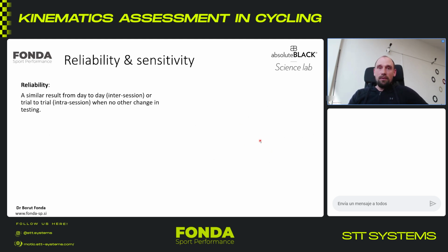They're both equally important. For example, you can have a very accurate system, but let's say you're measuring the knee angle of your cyclist, and you change absolutely nothing in the same trial, he just repeats it, and the knee angle changes by 5 degrees. I'm exaggerating, but just to illustrate.